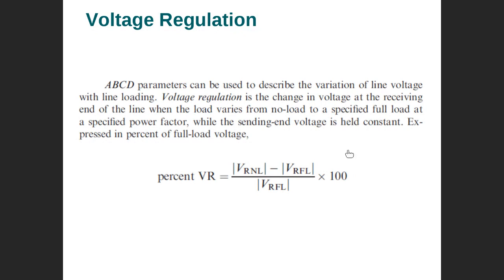Remember now why we use this voltage regulation: because you need the percentage to be within limits, maybe 5%, 4%. The change, how much change you want, from 1 per unit to 1.05 or 0.95, for example. So how do you work on these? You will calculate the voltage. I'm talking about now in reality.